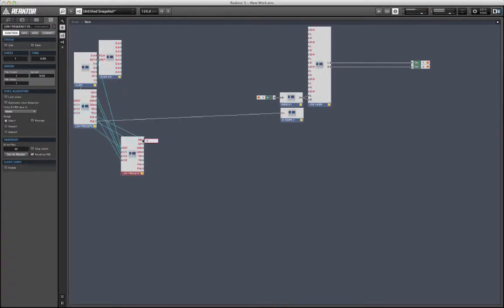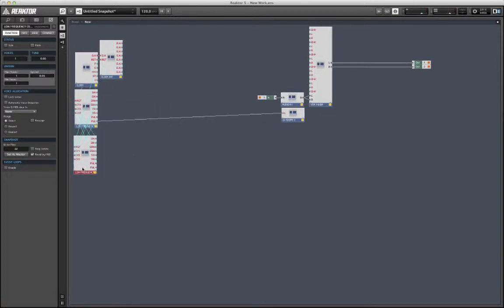And now we have the sine from the second oscillator running into the CV1 of the first LFO, saw to the CV2, and pulse to the CV3. These are all unattenuated signals. And coming out of the first, we have the same running to the second. This is a technique known as cross-modulation.